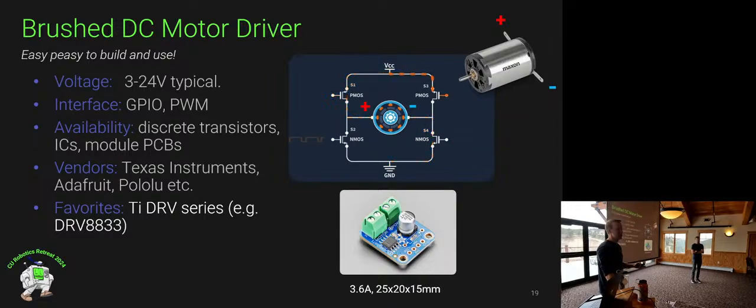That's going to dictate the size of your transistors, because current dictates how much heat is going to dissipate through those, and the channels in those transistors need to be big enough to handle large amounts of charge going through. If they're really small, in that high torque case, you're basically going to burn them up. They'll handle the high speed case, but they won't handle the high torque case. So I think basically you'd be stuck.